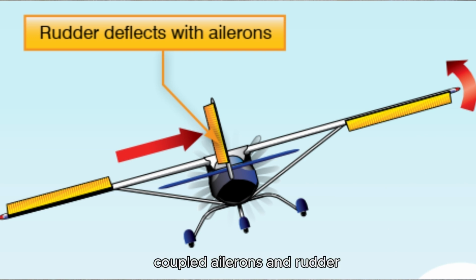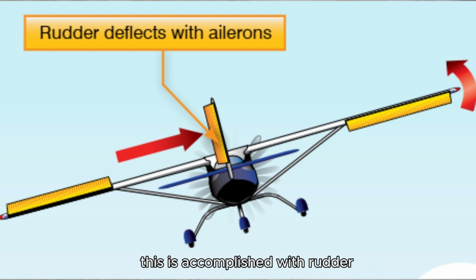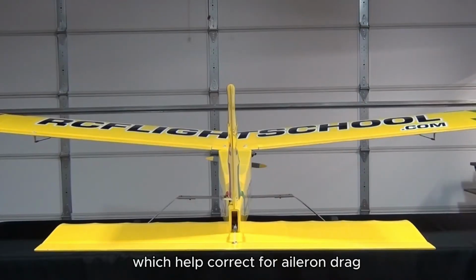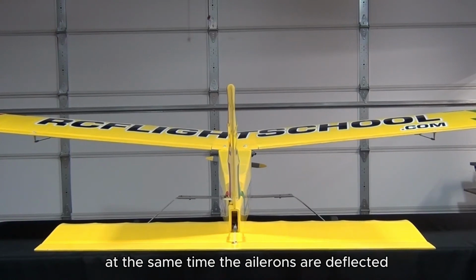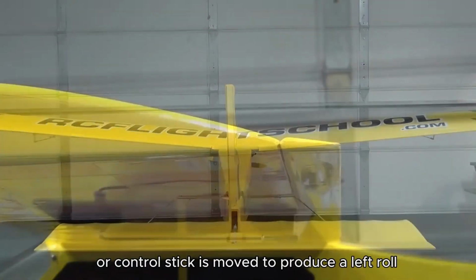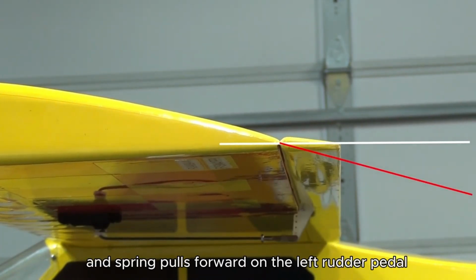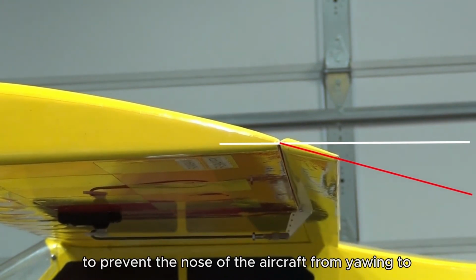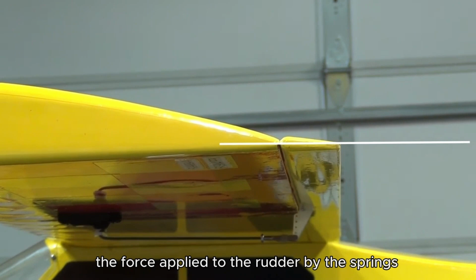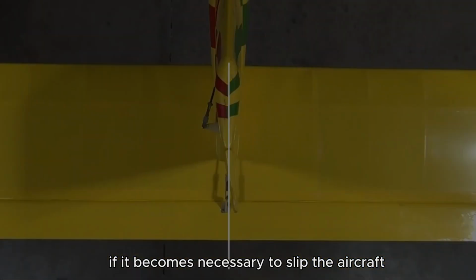Coupled ailerons and rudder. Coupled ailerons and rudder are linked controls. This is accomplished with rudder-aileron interconnect springs, which help correct for aileron drag by automatically deflecting the rudder at the same time the ailerons are deflected. When the control wheel or control stick is moved to produce a left roll, the interconnect cable and spring pulls forward on the left rudder pedal just enough to prevent the nose of the aircraft from yawing to the right. The force applied to the rudder by the springs can be overridden if it becomes necessary to slip the aircraft.